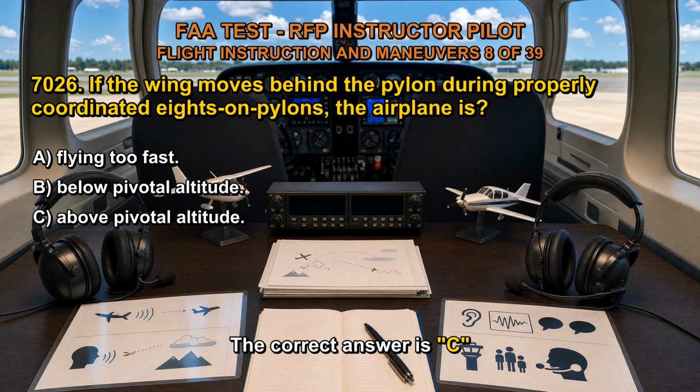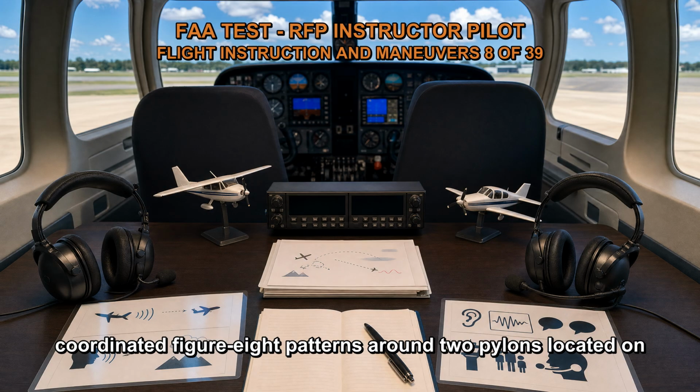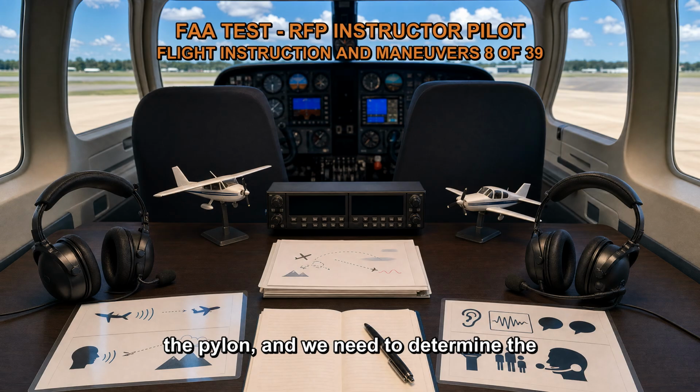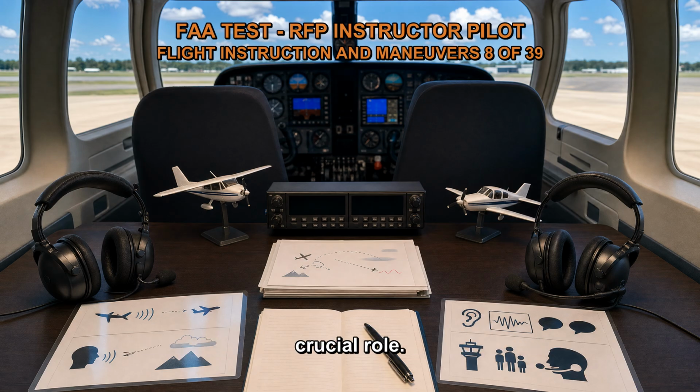The correct answer is C. Eights-on-Pylons is a maneuver where an aircraft performs coordinated figure-eight patterns around two pylons located on the ground. The question states that the wing moves behind the pylon, and we need to determine the meaning of this situation. During the maneuver, the pivotal altitude plays a crucial role.